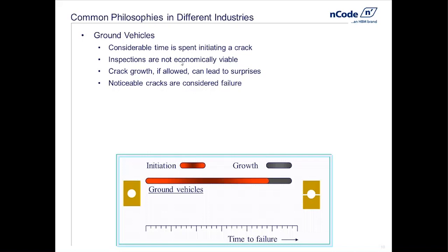So in general, in the ground vehicle industry, we tend to consider noticeable cracks to be failure. Therefore, we're not concerning ourselves with crack growth, and we're designing up to this point right here. Let's not let a crack start.